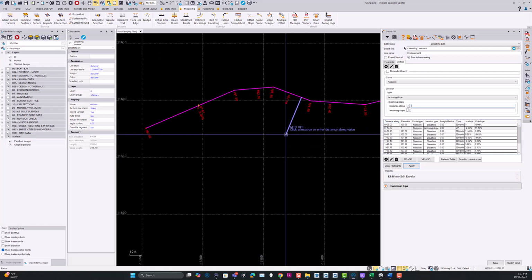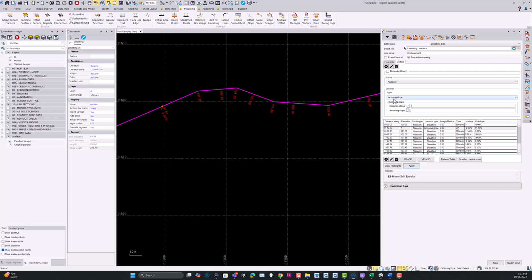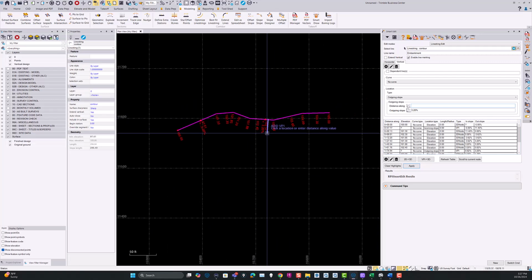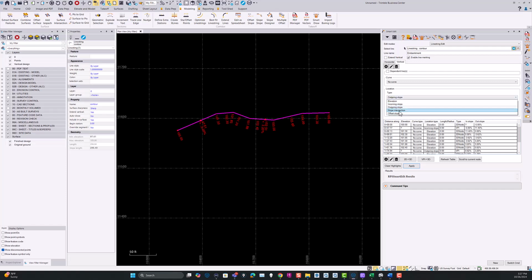If you want to do an outgoing slope, let's pick another one here. Let's do an outgoing slope right here somewhere. So I'm going to go outgoing slope, and if I click on a point right here, I can say that outgoing slope would be, let's say, 3.2% positive, and press enter, and then that will calculate the elevation at that point, and again set the elevation on here as a calculated value of 102.51. So if I scroll down here, see if I can find that in the list somewhere, 102.51, it will be this one. It's set by outgoing slope, and you can see the elevation values computed on the line here. The slope is doing the same thing, but in that case you put in two slopes, an inbound slope and an outbound slope, and it will calculate where that point should lie and set the elevation.